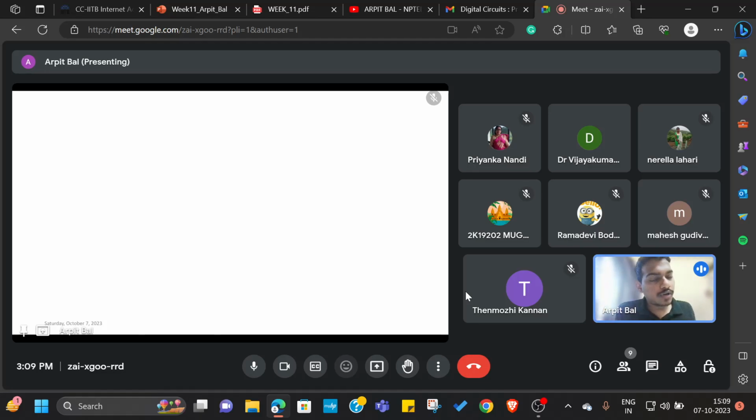It can be used for temporary storage of information, and these two instructions, PUSH and POP, are related to that operation of the stack. There are a few points you will need to keep in mind: the stack grows backwards into the memory.